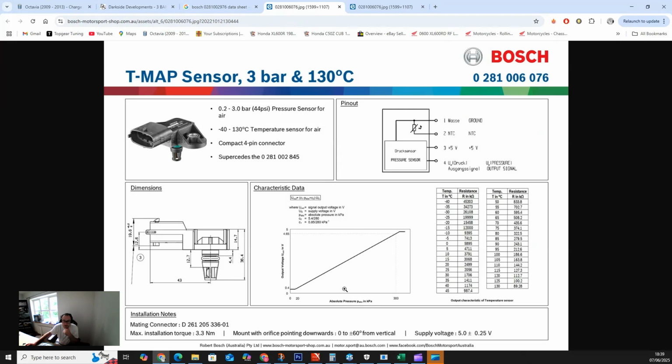So the temperature here, as I say, I was looking at IATs. The IAT values I was looking at for intake air temps are pulled from the map sensor, which is really valuable in the sense that it's post-charge cooling, and it's right before the EGR or anti-shudder valve in these. So it's a very good indication of what your temperature is actually, or as close as you can read before it gets pulled in and combusted. So that's really valuable for us.